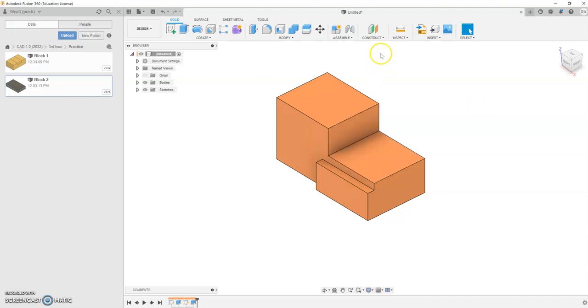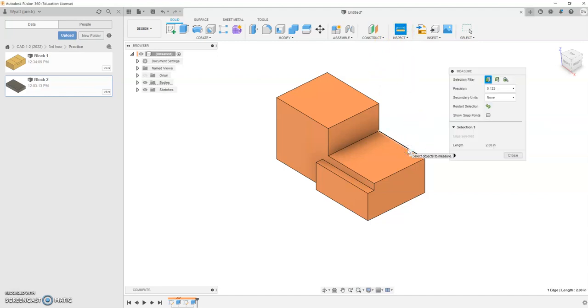All right, so to make this happen, I need a part that goes into here, let's say to start with. So I need to measure this. Then come up to where I inspect, if I don't remember. That line is 2 inches, okay. Inspect again. Oops, nope, that's 90 degrees, not what I wanted to do. Repick my inspect. That line is 2 inches, okay, great. And there, that line is 1 inch. So I need a 2 by 2 by 1 inch thick block.